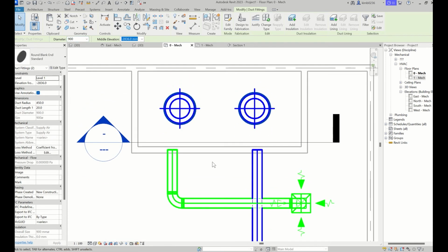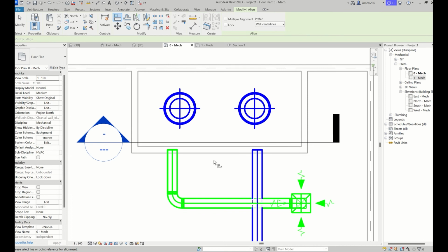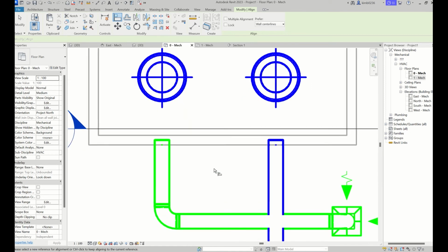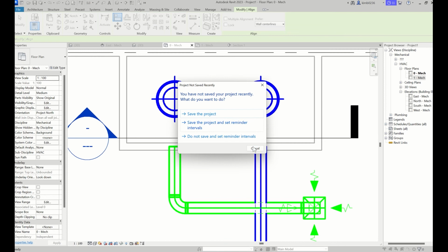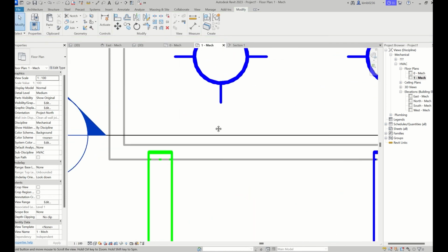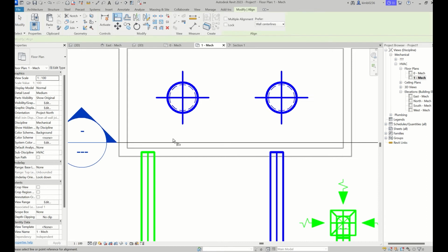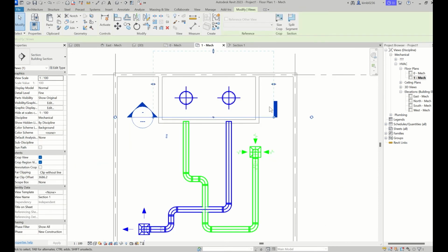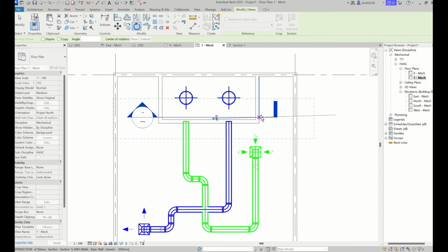Nice. Now these won't connect properly unless they're aligned. So you can use the align tool and select the center point of the vertical ducts, and then we can bring these smaller horizontal ducts to it. Cool. We'll do the same on the first floor. We'll select the center point with the align tool, and we'll bring the horizontal ducts over to it so they're nice and lined up.